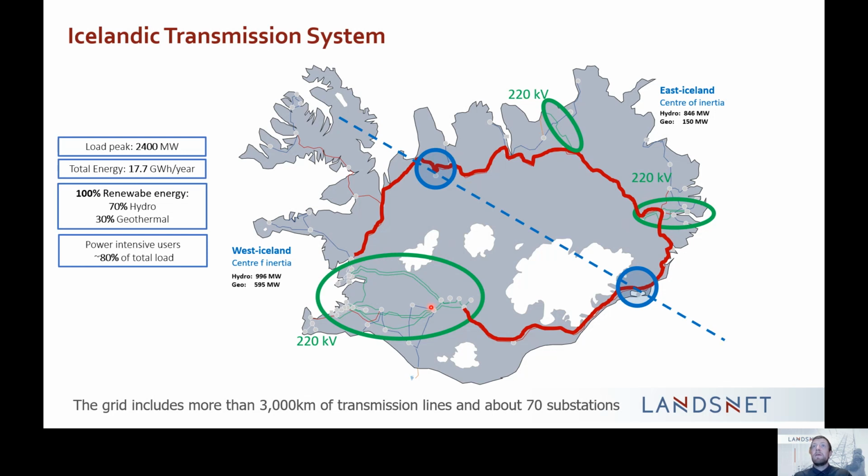And again, this is just a conventional special system protection, just using overload, overpower protections to open a breaker here on a double bus at a hydro station, and in another substation here, creating these 2 islands to mitigate the response during those large disturbances, large imbalance events in our system.